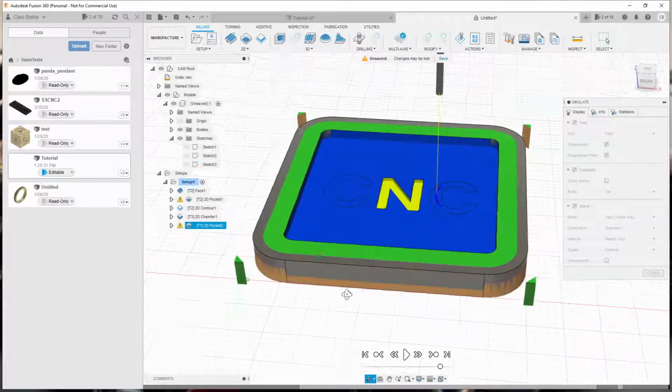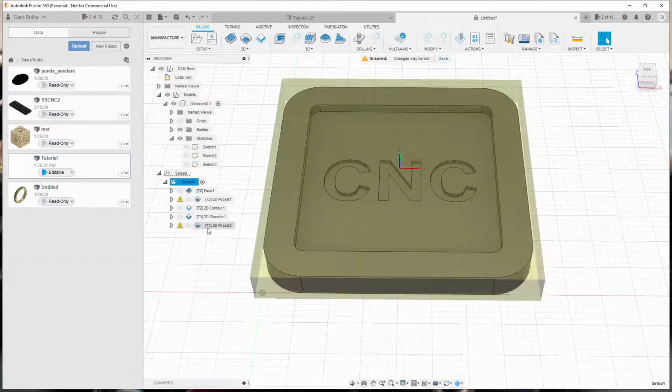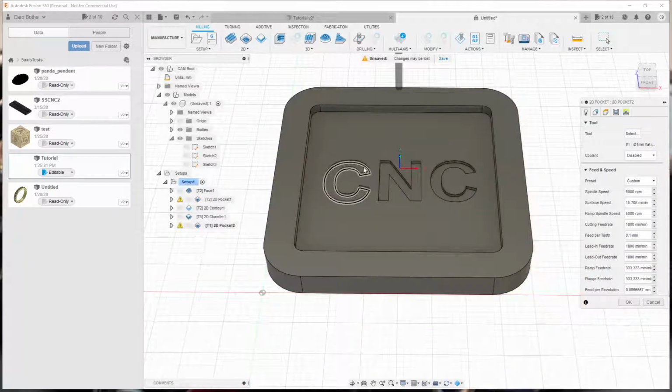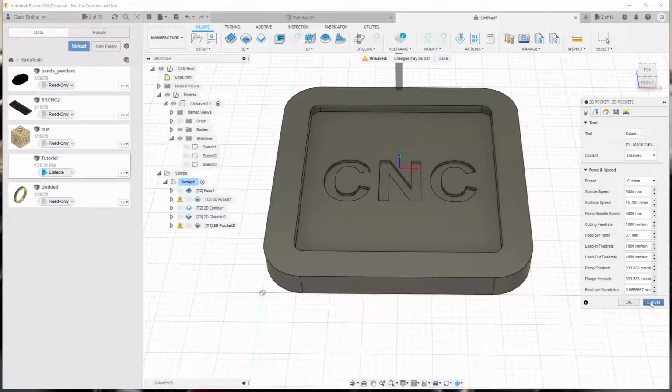So I wonder why it couldn't get into there. I think maybe that cutter is a little bit too fat to get past these curvatures. So we may have to go in and edit that to be a smaller cutter and see if we have better luck. Of course, in the real world, you'd be going in your workshop and making sure you actually have a smaller cutter. Or you'd be changing your drawing to be a little bit thicker, a little bit bigger. So let's go that way around because I've been bragging about how good parametrics is. So let's just cancel this out of here.